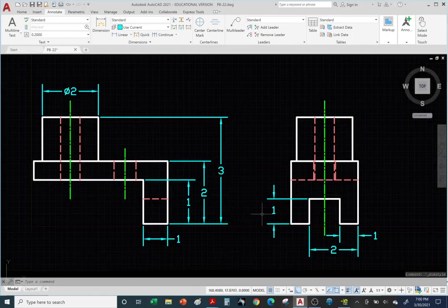Now we're in inches, but you know what? We should add 2 decimal places. When dealing with inches, if you don't know how many decimal places to use, start with 2 decimal places. That's a good starting point. Okay, so let's change these to 2 decimal places.